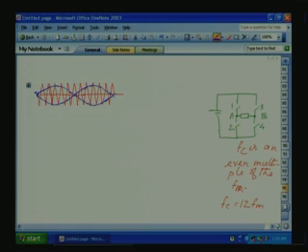Only thing, this is an odd multiple, so the zero crossing is happening somewhere here. Now, if you draw the PWM, that means FC is 12 FM.